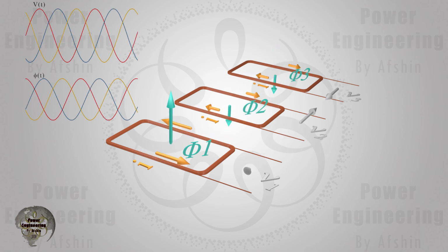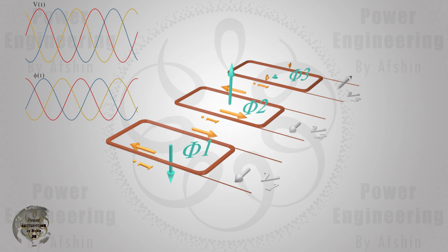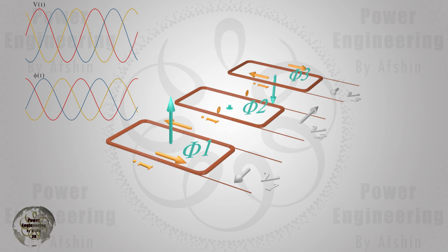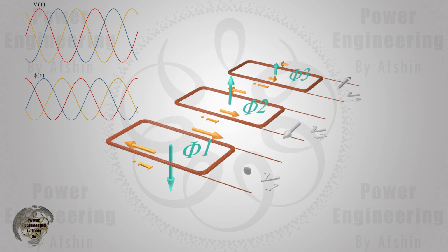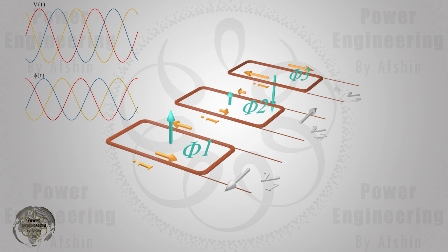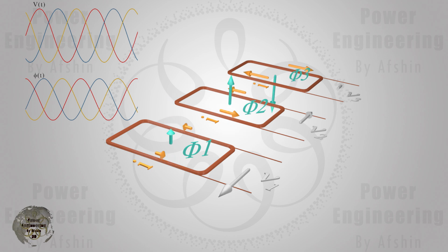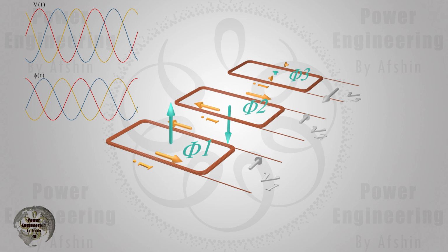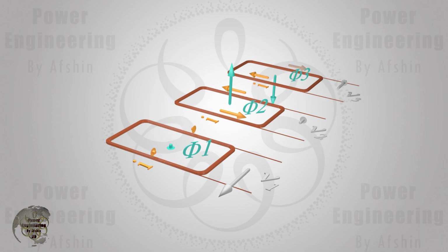If three similar coils are present and three-phase voltage is applied to them, the resulting outcome will be as observed. The phase difference of the voltages is 120 degrees. As you can see, due to the phase difference of the voltages, the fluxes also exhibit the same phase difference. In other words, the fluxes have a phase difference of 120 degrees in terms of time.